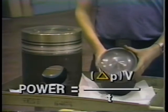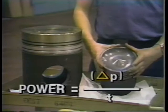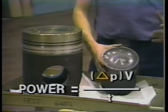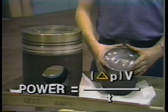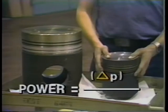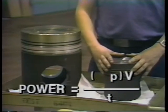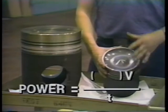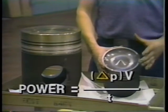The volume, or the size of the piston we have in the cylinder. The rate, or the RPM. This engine you just saw runs about 1800 RPM. We can run it as little as 1000 RPM. Or we can change the pressure. These engines are designed to run at about maximum pressure, so we can't increase the pressure to effectively increase horsepower.